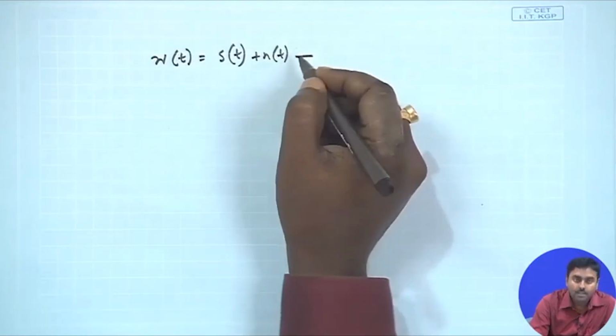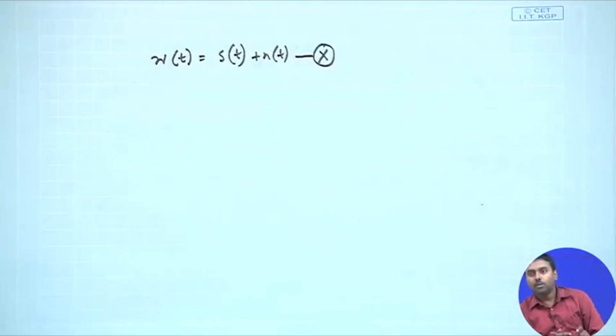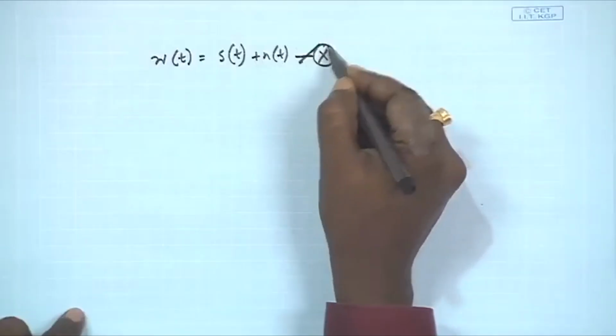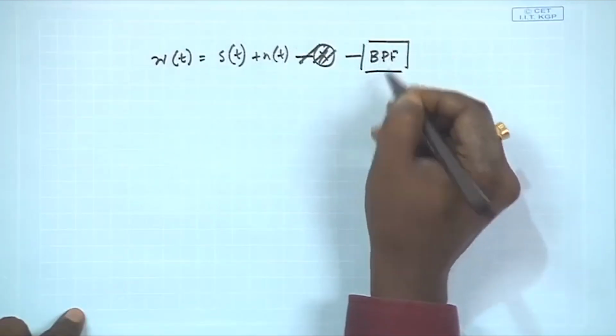Okay. So, in the very beginning of the receiver, you will have a multiplier. SSB is also demodulated in a similar way as DSB is demodulated. So, you will be putting a multiplier, but before that we have to employ a band pass filter. So, this should not be the first part, there should be a band pass filter.